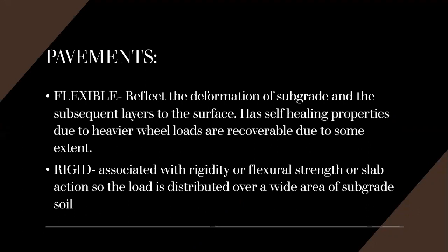Now, flexible usually, right, as usually asphalt is laid with no reinforcement or with a specialized fabric reinforcement that permits limited flow or repositioning of the roadbed underground changes. However, the rigid is associated with rigidity or flexural strength or slab action so that the load is distributed over a wide area of subgrade soil.